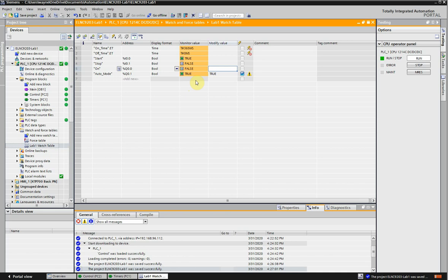And you saw that with the Rockwell PLCs with internal tags that we were toggling on and off that weren't actually being used anywhere. We were just using those as temporary bits. We toggled the bit on or toggled the bit off. So that's basically what we're doing here. So this only works if there's no ladder logic actually turning this off.